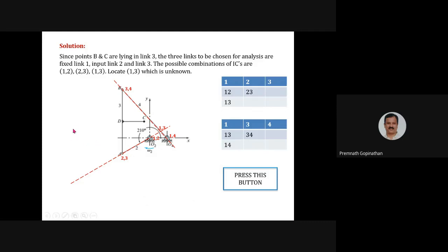And always you can see that the velocity of point 2 3 will be equal to the distance 2 3 1 2, that is the distance, into the angular velocity omega 2. After finding out that velocity, you choose a particular scale and draw it perpendicular to the line of centers from the point 2 3. So from the point 2 3, you draw the velocity vector corresponding to its magnitude, and it is perpendicular to the line of centers, right?